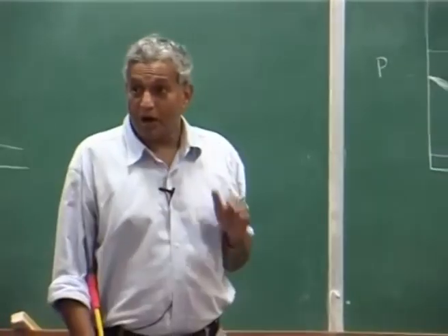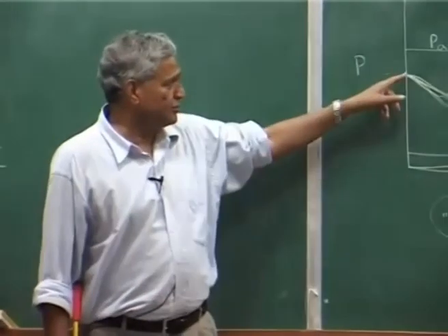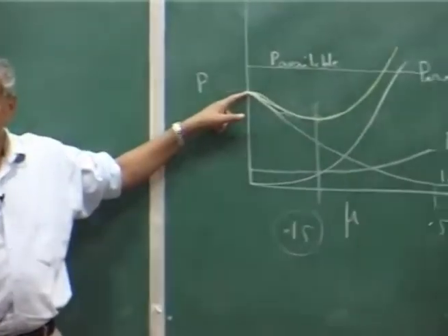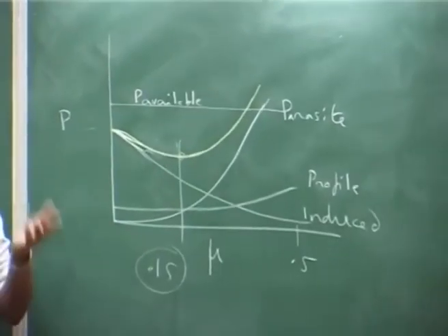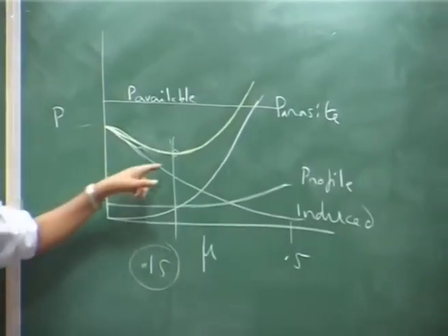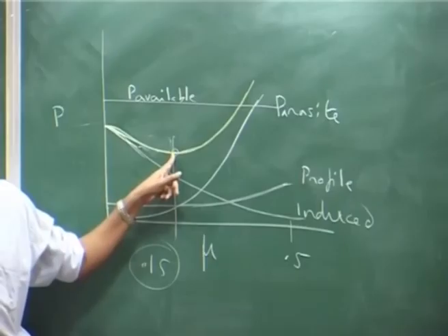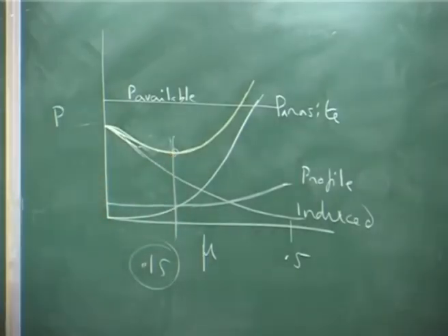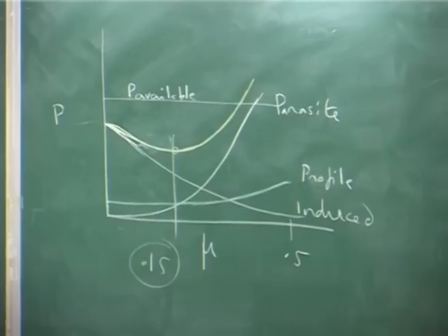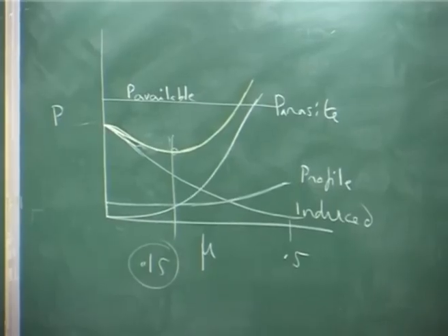You can auto rotate in hover, but the descent velocity will be much larger, whereas if you auto rotate at the minimum power, the descent velocity will be less. Of course, he is moving forward, please understand, he will come forward.